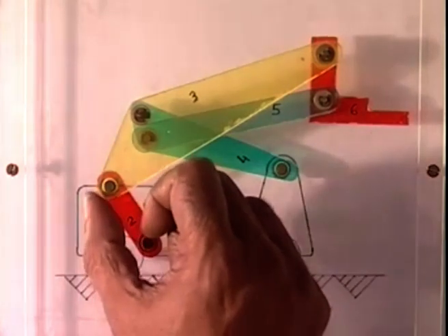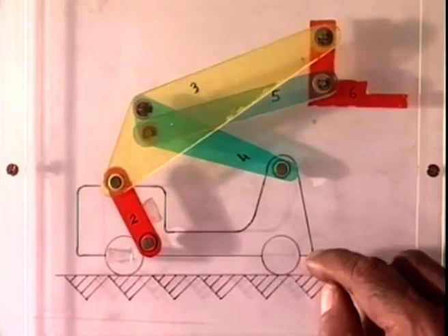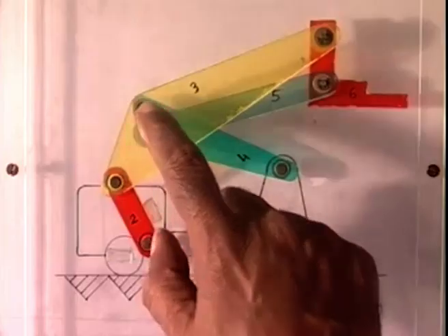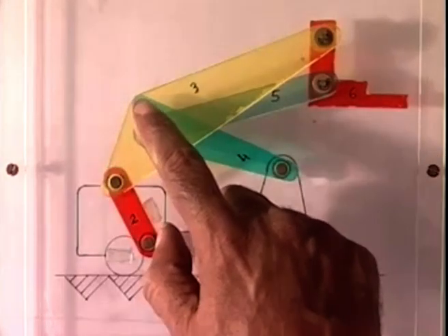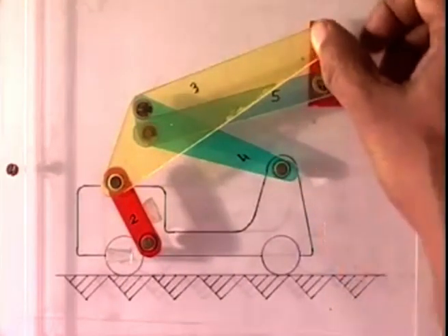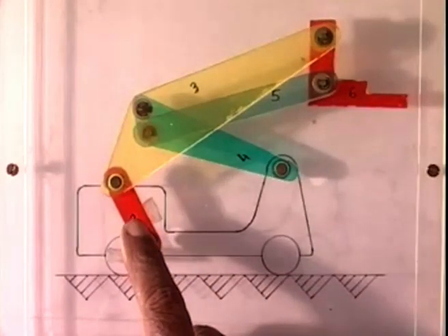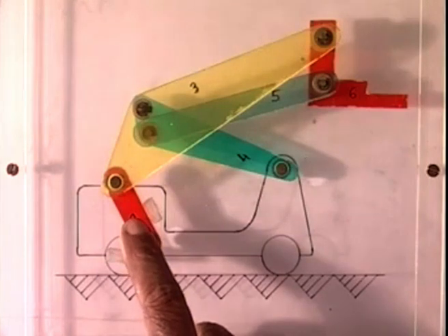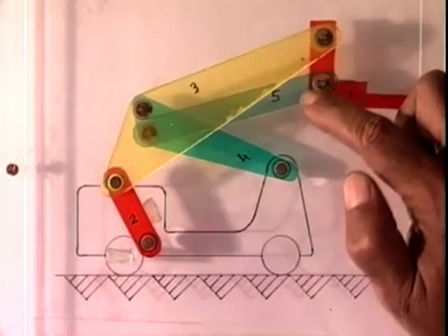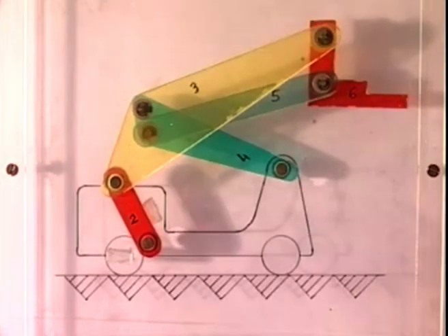Next, we chose O4 conveniently on the body of the truck. Then removed the slider and got a coupler point here at C such that O2, A, C, O4, these four linked, has a coupler point B which has an approximate straight line path, and the movement along that straight line path is coordinated with the motion of the input crank. In the third stage, we had chosen this point D again conveniently on the body of the fork, such that a second point is guided along the same vertical path.